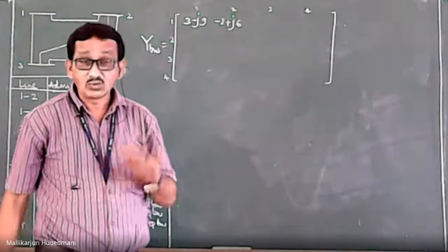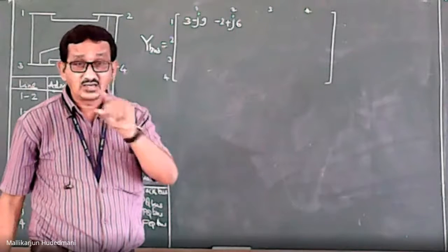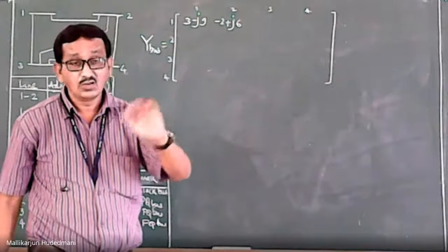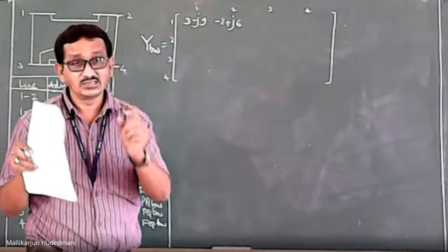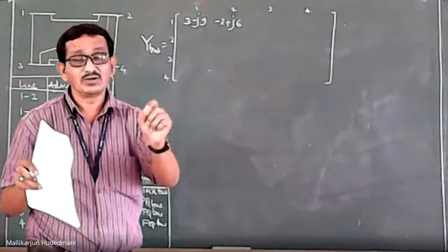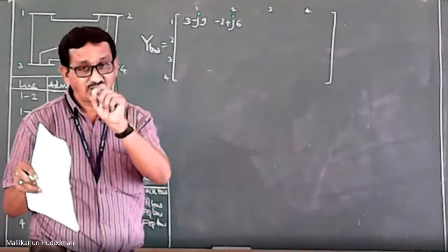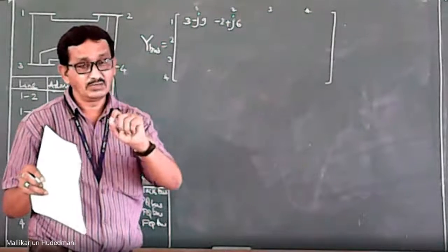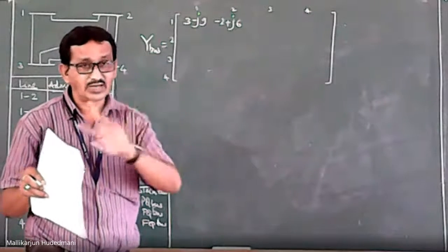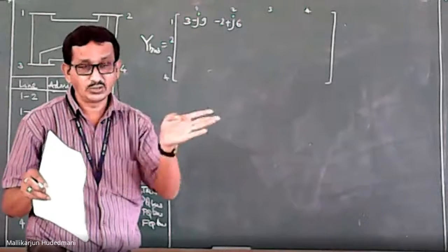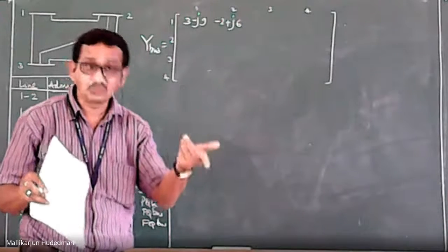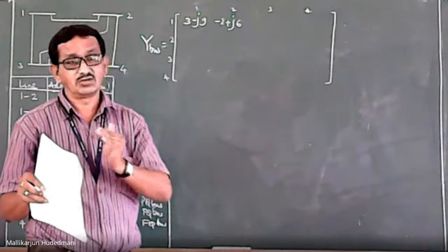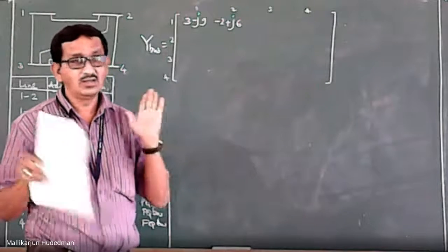When I announce that number, the elemental data between those two buses should be put with negative, because when I solve by nodal analysis, negative terms come out because of the voltage from which the connection starts, I mean the bus, and lands on a particular bus. When I take current to flow V1 minus V2, the second term is naturally minus V2. That minus will come to the admittance representation for the simplicity of mathematical arrangement.